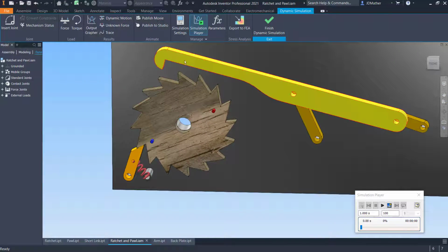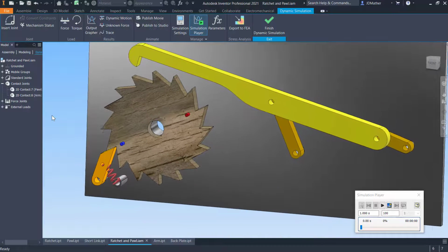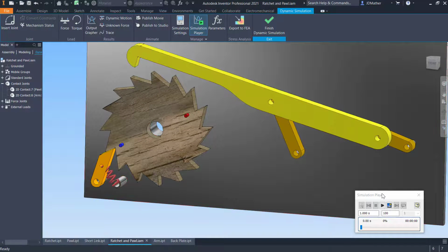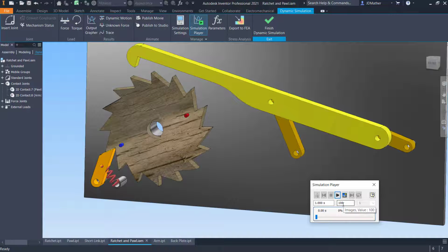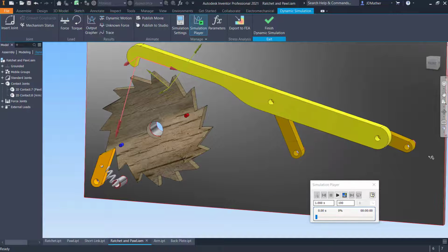So we can do this contact one of two different ways. We could either do it as 3D contact, or since these stay in the same plane, we could do it as 2D planar contact the way I did. Experiment with it both ways and see which solution works better. You may need to increase the number of calculations and experiment with the amount of spring force, and also experiment with the restitution and the friction value. You'll have to put an imposed motion on the motor to drive this. So I'll leave the rest of this for you to experiment using what we have learned so far.